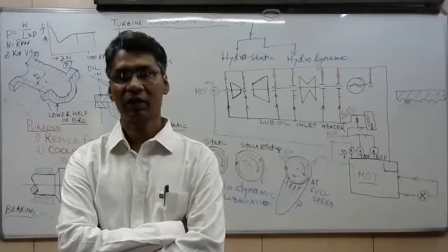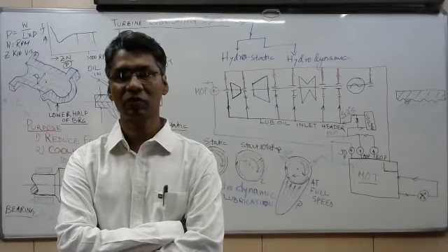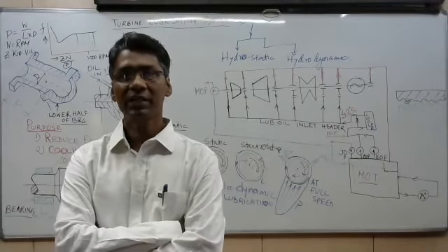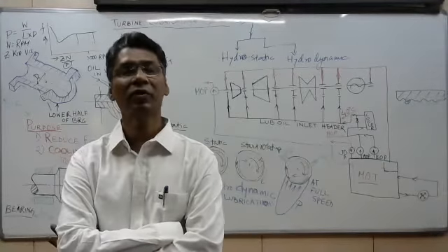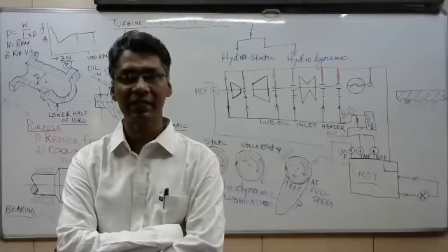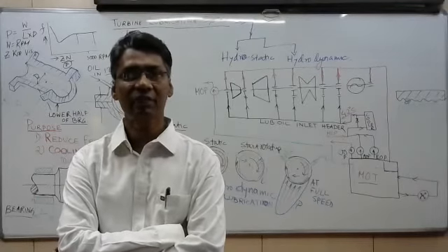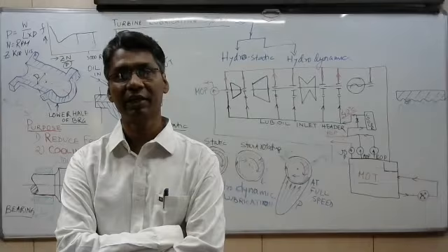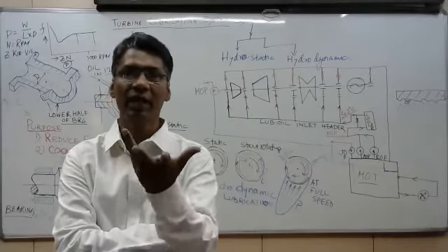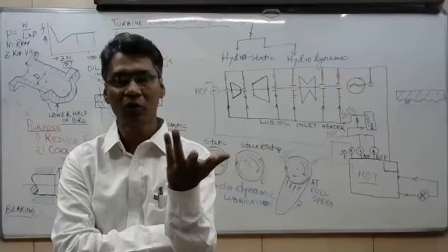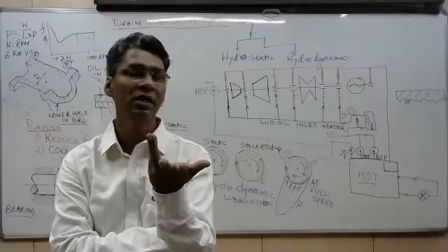Can we say it is for deaeration purpose also? For deaeration purpose, you see the outlet head of the lube oil is very big in size. Also the vapor extraction fan, at least one is running continuously. So that is providing cooling as well as normal vapor removal from the top of the tank.